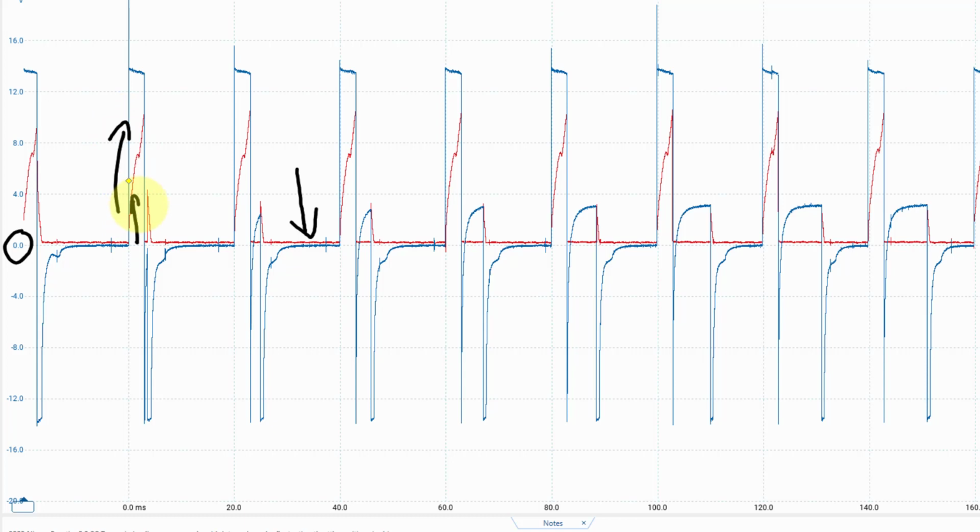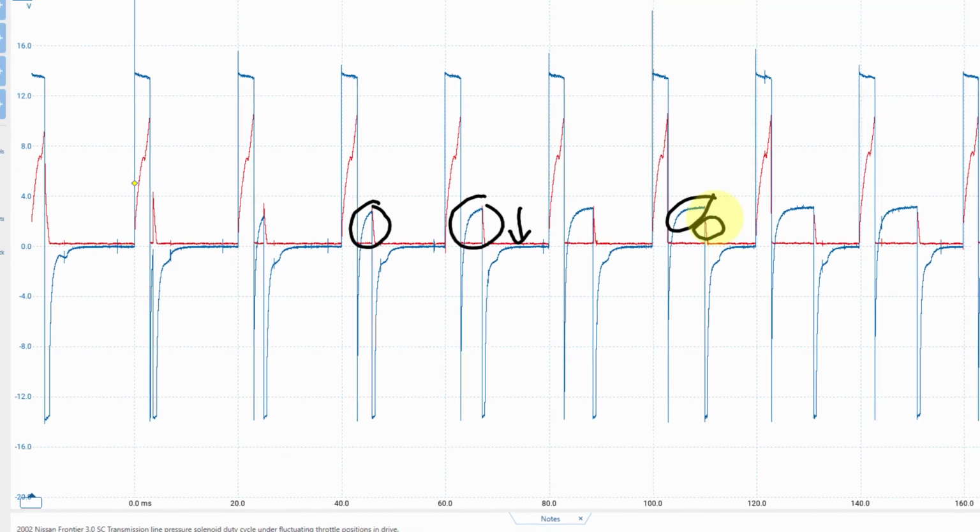And this duty cycle that's taking place is showing us the amount of time we're dutying, which is actually controlling how much time this amperage stays at 0. And the 0 amperage is going to be an increase in line pressure. And we can also see how this duty cycle is impacting this little blip right there on the amperage scale.